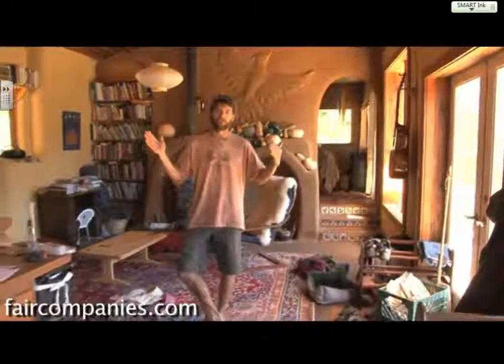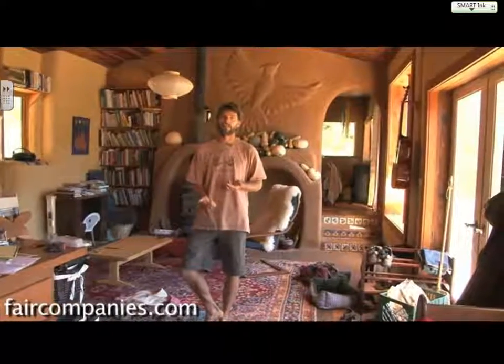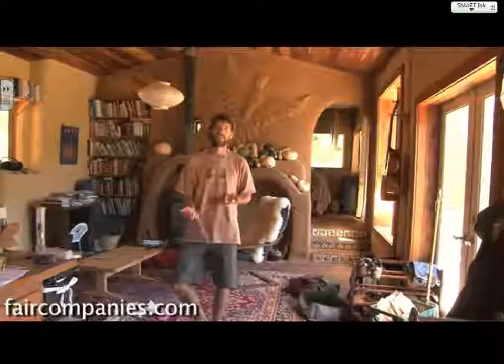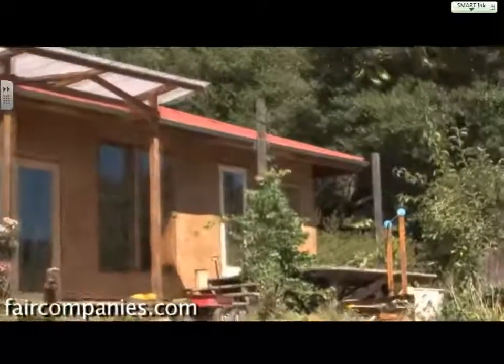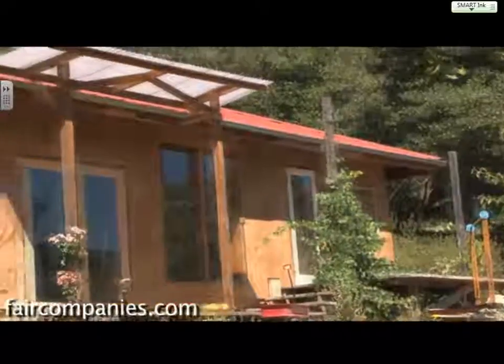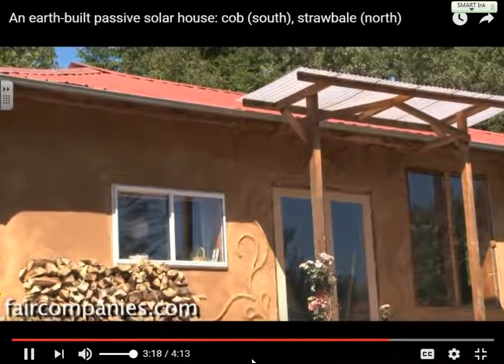The way we do it here, at night we open up all the windows and we let the cool night air come through the house, and that discharges any heat that's been stored up in the thermal mass during the hot day. And then in the morning we close up all the windows and just keep that coolness locked inside the building. In the winter it works pretty much the same way, except of course you don't open the windows at night, you leave them closed.